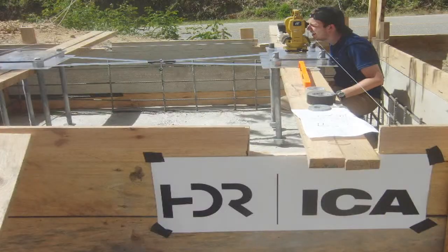And before we do that, though, we've got to get in there and we've got to set the anchor bolts in their proper locations. This is the most critical operation that we did the whole time. If the anchor bolts aren't set right, there are 2 things that will happen. One is when we go in to put our base plates in place, they won't fit. Okay, so that's one thing. So we've got to be able to have these things positioned properly from this grouping to this grouping. That relative position needs to be accurate.